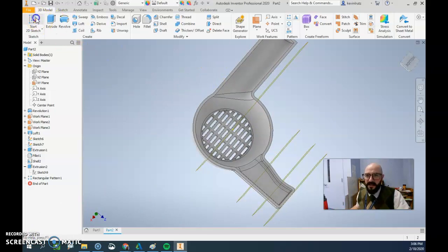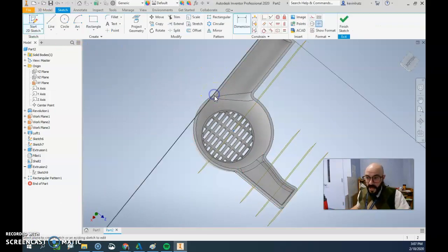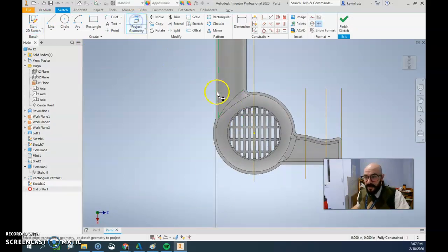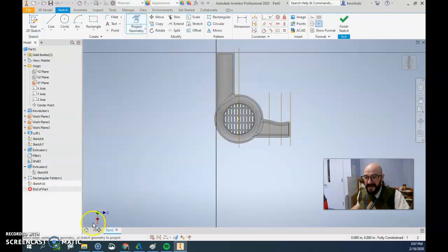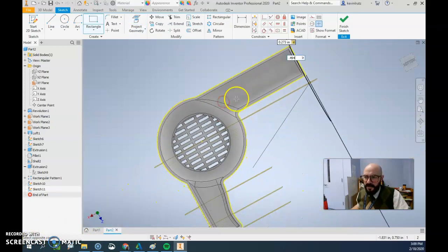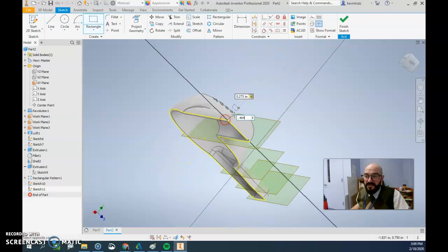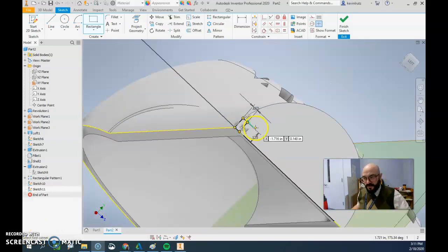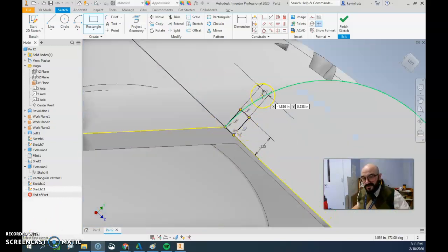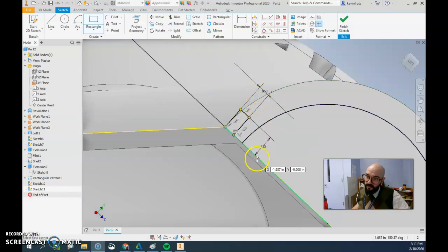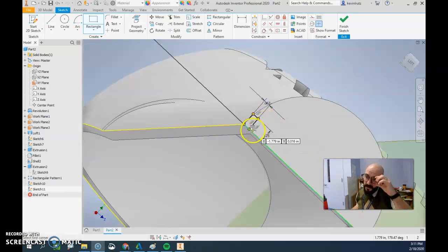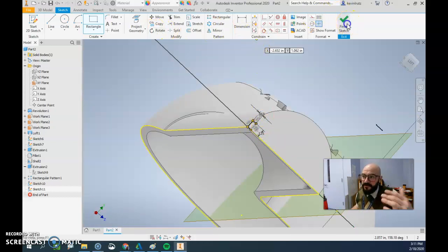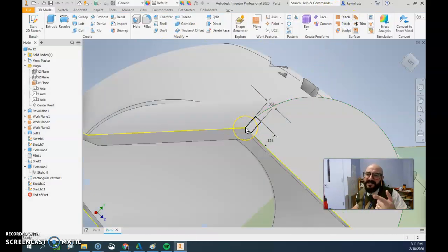We are going to flip it upside down, start a sketch on the bottom face, and we are going to pick Project Geometry, and we're going to select the entire outside of the ring, of the thing. Alright, so we selected that, we right-clicked and said OK. Now we're going to sketch on this nozzle, and we're going to make a box as I show you, right? Okay, so this box is 0.0625 tall and 0.125 wide for this face. And now what we're going to do is finish our sketch, and it's right at this tippy top corner. Don't miss that.